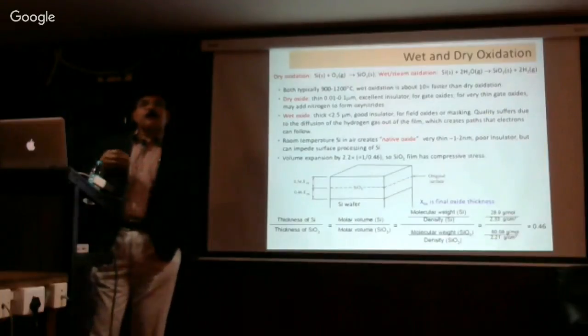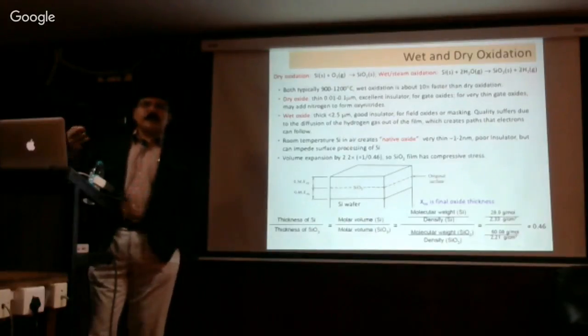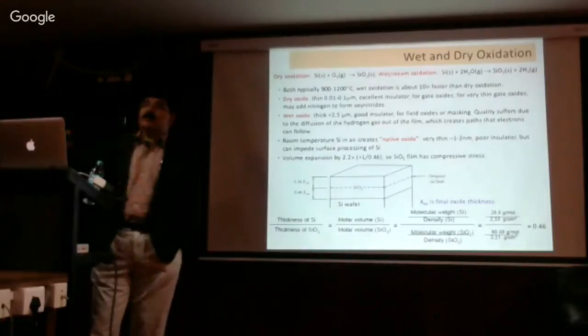But imagine that if you leave oxygen very close to silicon, then you have an oxide. So if you deposit high K, let's say hafnium oxide, on top of silicon, you will automatically have an interfacial layer of silicon dioxide. That is actually the biggest problem. That's why the oxide quality, the interfacial layer, is very difficult to control.